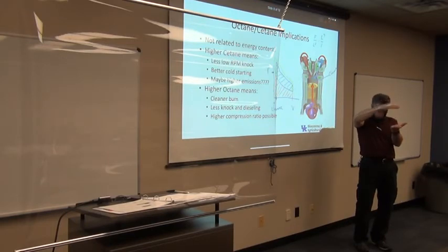If that auto ignition pressure of the fuel is really low, and in a compression ignition engine I inject that fuel in there, that fuel starts to burn right away. Well, those particles, those droplets, the atoms of fuel, have not gotten to mix with all the oxygen in the outer edges of that compression chamber.